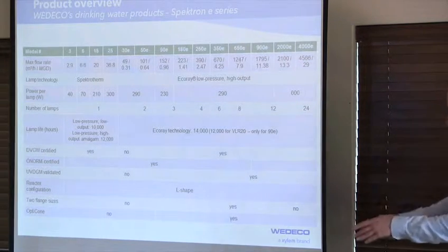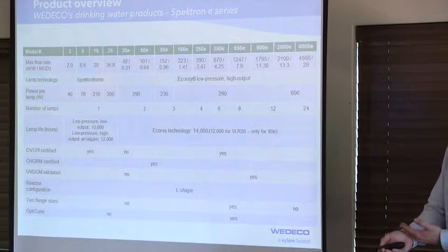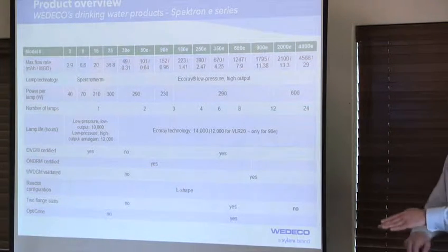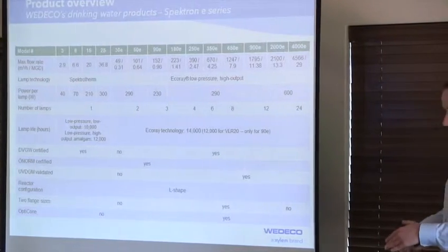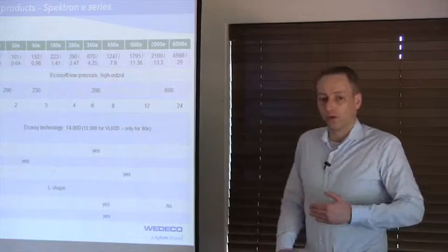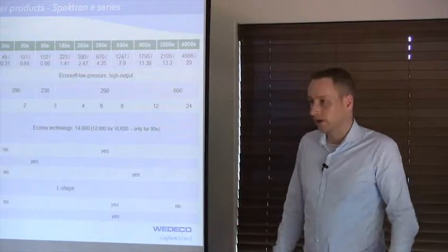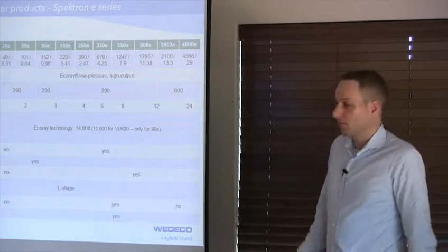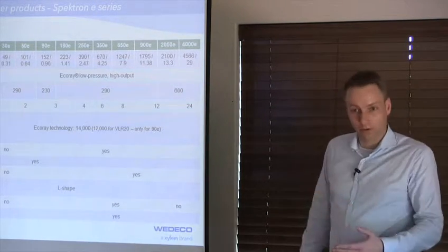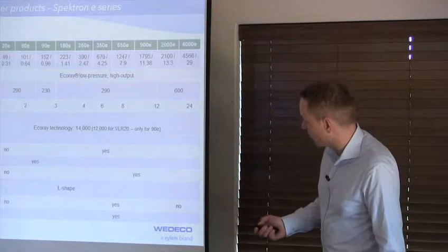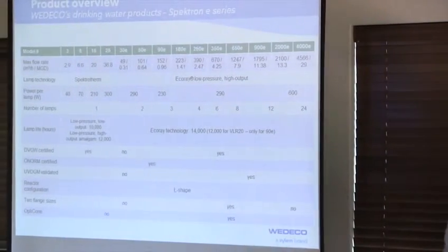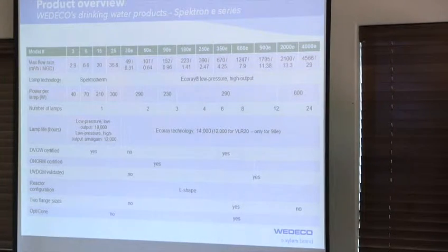So you know the system was tested for a flow of up to 60 cubic meters, and it achieves this performance for a reduction of these target surrogates. Then we know that in a real world application it will be sufficient for a 3-log reduction of cryptosporidium, for example. The US EPA, for DVGW and ÖNORM, just do it with one very hard to kill target organism.